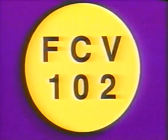Let's review the location of indicating letters. The letter for the process variable is always first. If the instrument indicates, records, or performs some other function, or if the device is a control valve, there should be a middle letter to indicate this. Last, there's a letter that stands for the actual name or function of the instrument.